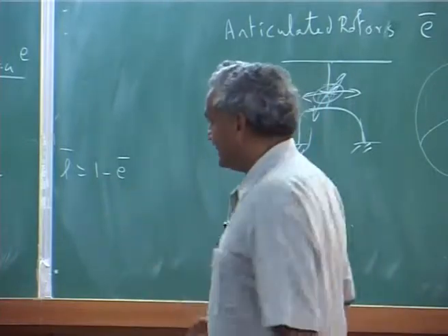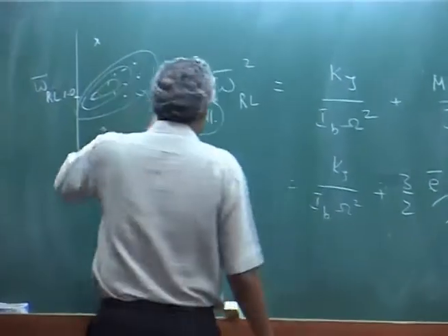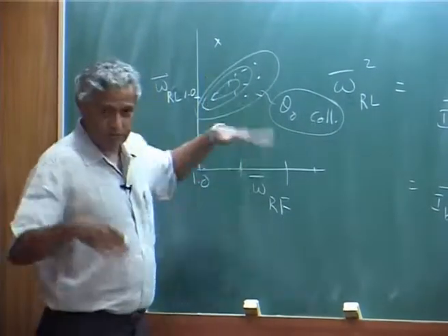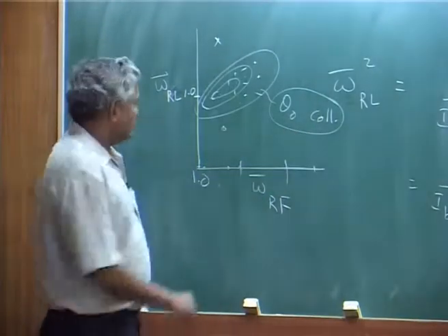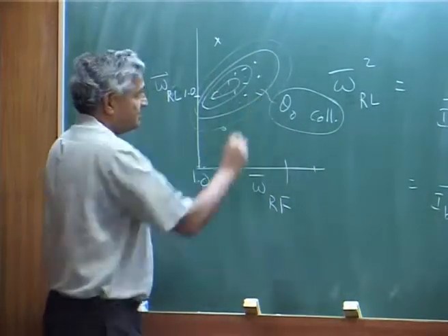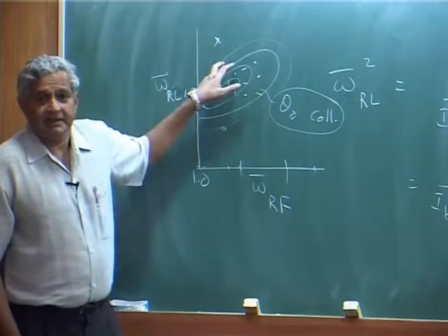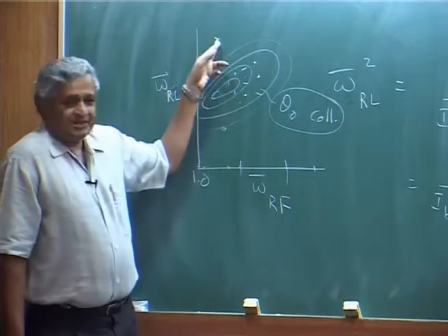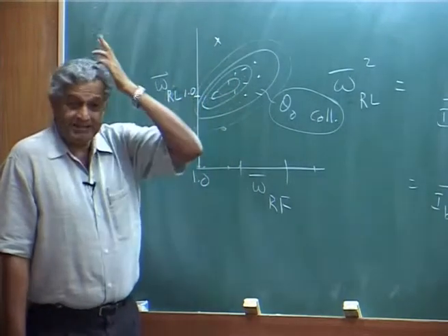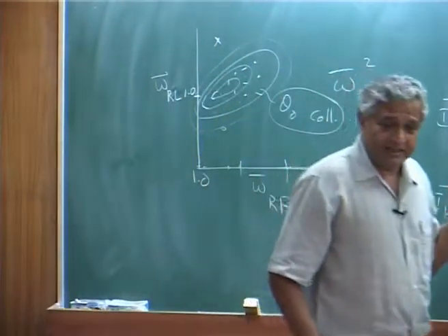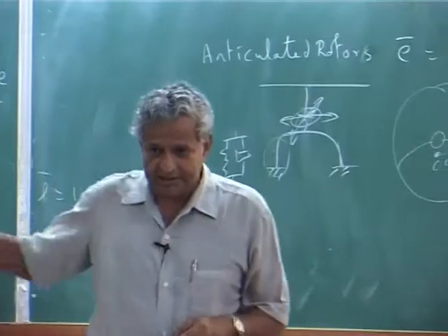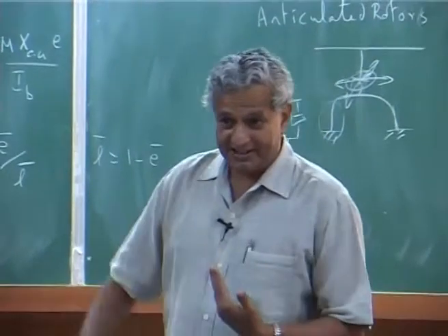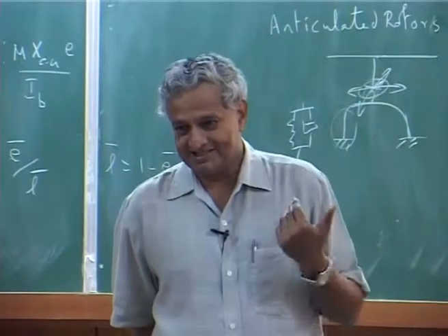See, this bubble will keep on expanding. Of course, this is based on a very simple calculation, not with a stall model and other things. If you use a more systematic analysis, the bubble may become like this for another pitch angle. But if you know that you are never going to operate at this angle of attack or pitch angle of the blade, it is fine. Because this is all done in hover condition, all these calculations. Now, suppose you say I am going to do it in sideward flight, climb flight or descent flight, various types of flight conditions.